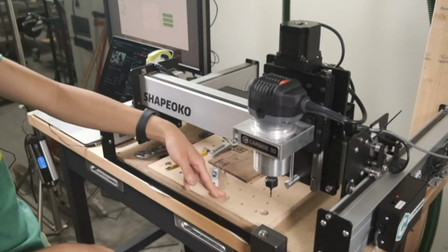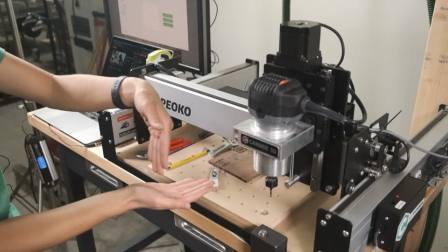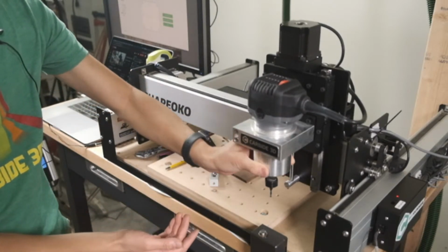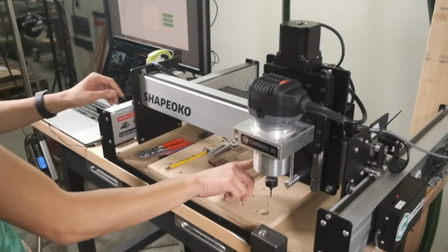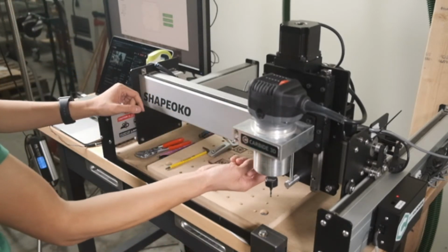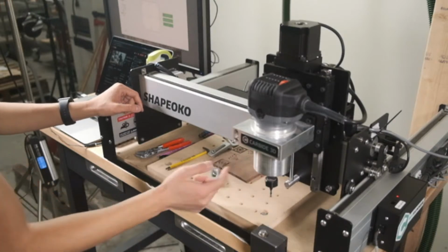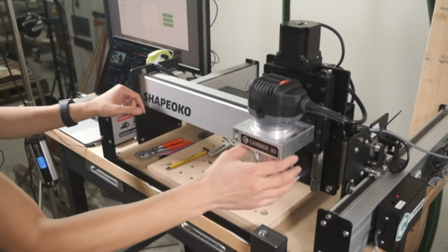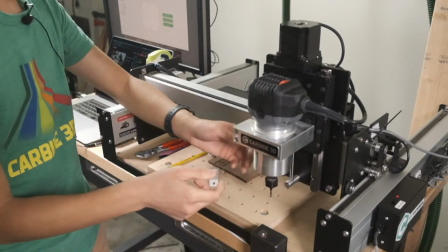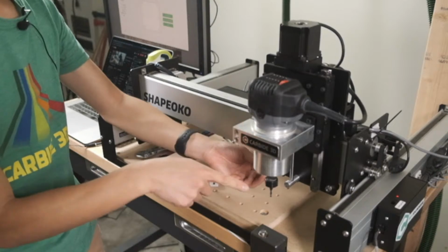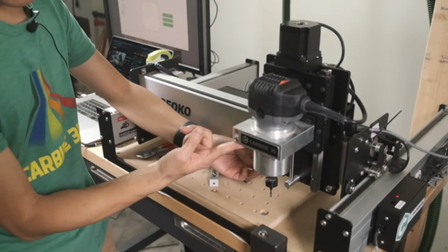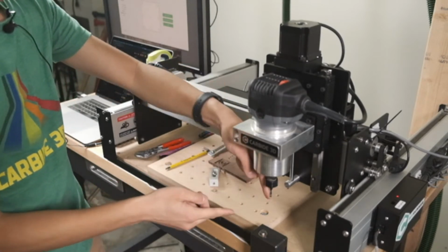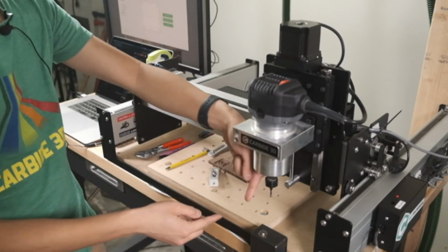So that's going to introduce some errors, some potential layer lines as you step down deeper and deeper. The cut forces change. It might kick out the spindle or pull it down. So loose V-wheels is a big issue as to why your cuts might not be accurate. And it can also cause your zero to change because as you cut, if the forces tilt this upwards, the offset in the Y-axis is going to be different.